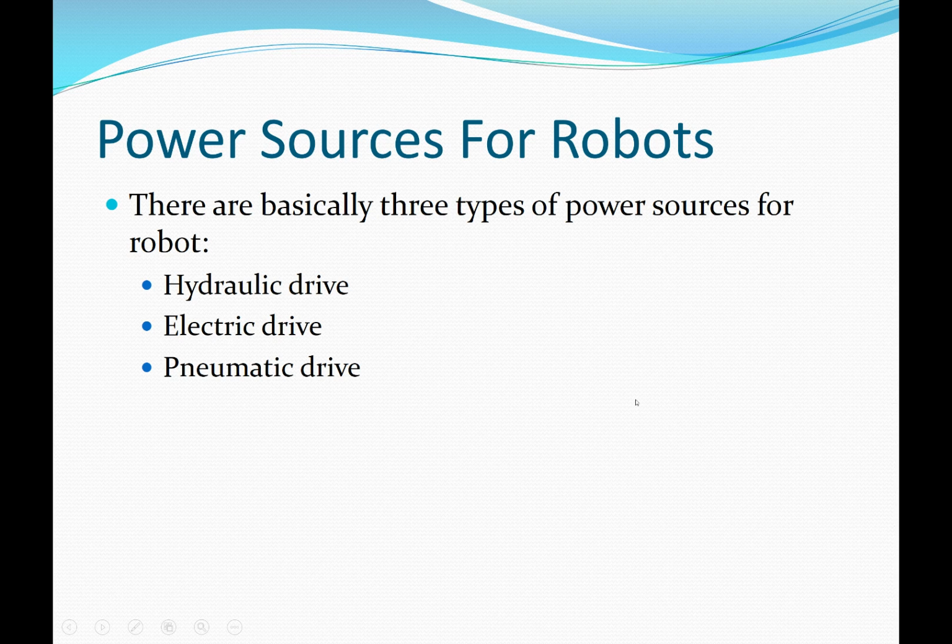You'll use pneumatic drives in places where you're dealing with things such as natural gas and petroleum, where it's very flammable. You might want to avoid the use of electrical motors there. Hydraulic could be used in those situations as well.